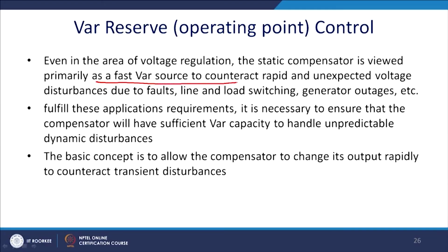So, VAR reserve. Even in the area of voltage regulation, the static compensator is viewed primarily as a fast source to counteract the rapid or unexpected voltage disturbance due to fault, line load switching, etc. To fulfill this application requirement, it is necessary to ensure that the compensator has sufficient VAR capability to handle unpredictable dynamic disturbances.